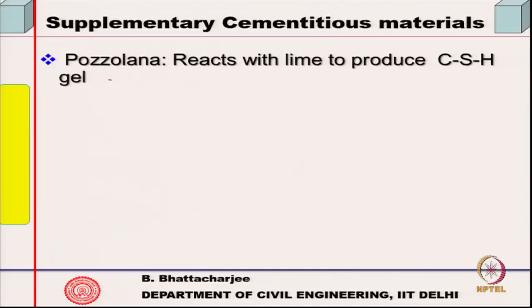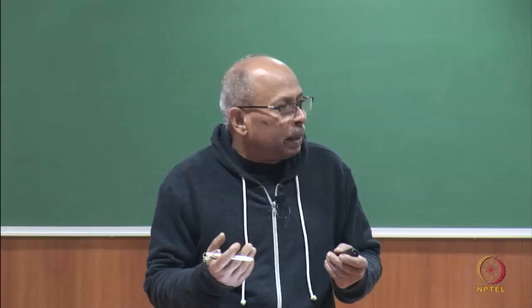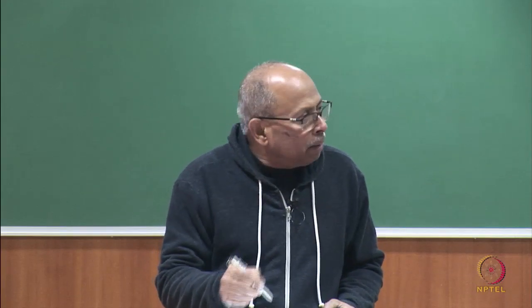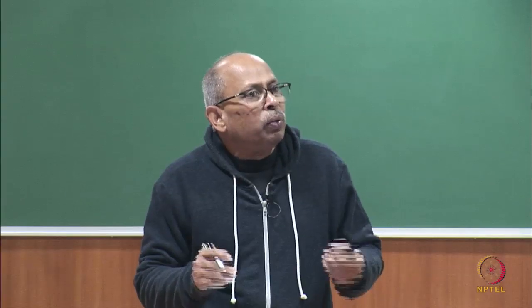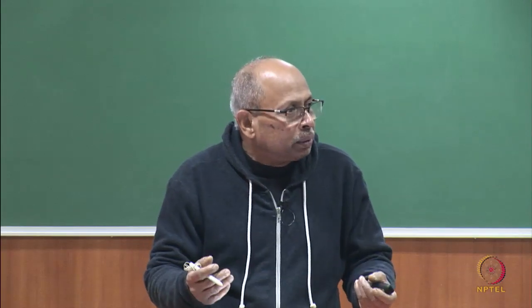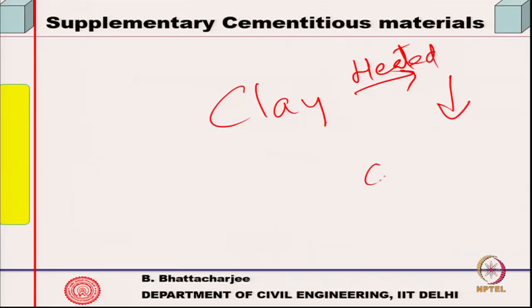Okay. So, the pozzolan's name came from volcanic ash. Now, volcanic ash is the ash that comes out in a volcanic eruption in the beginning. So, what would have happened actually, the clay would have been subjected to a lot of heat, right, a hot powdery thing, ash, and this would settle to the atmosphere. That means around 25-30 degrees centigrade, suddenly it is exposed to 25-30 degrees centigrade. So, clay heated and cooled rapidly.